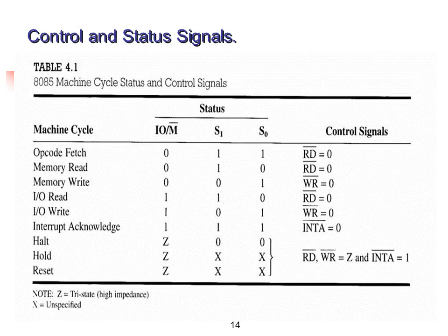The flag register of the 8085 microprocessor. I already mentioned to you that the flag register of 8085 has 5 active flags, that is sign flag, zero flag, auxiliary carry flag, parity flag, carry flag. The sign flag is set whenever there is a carry forwarded from D7 bit to D8 bit, and the zero flag is set when the result of the ALU operation is 0, otherwise it is set to 1.